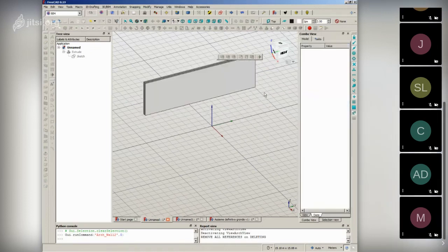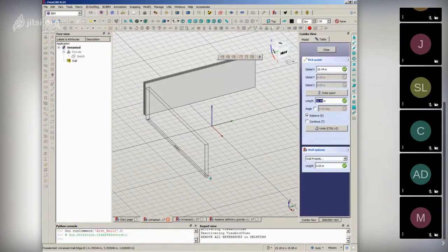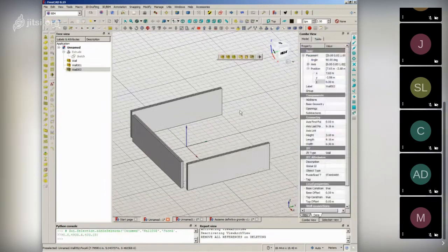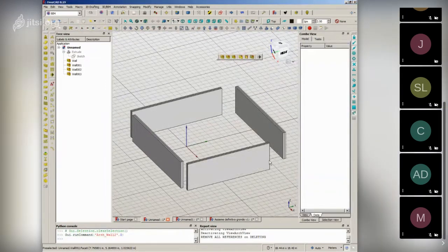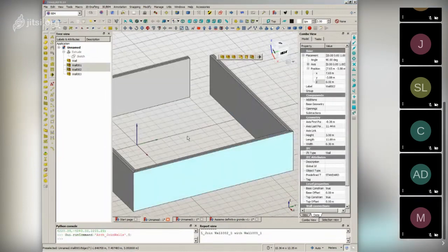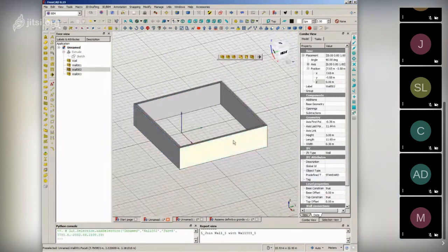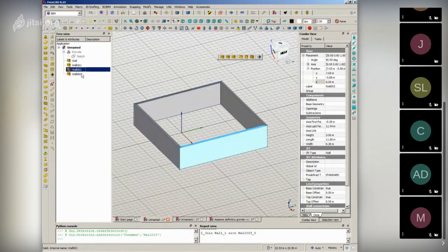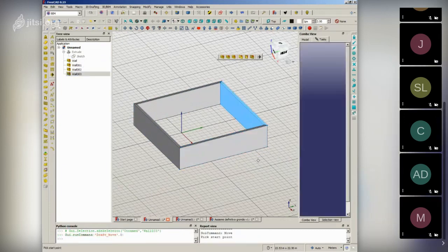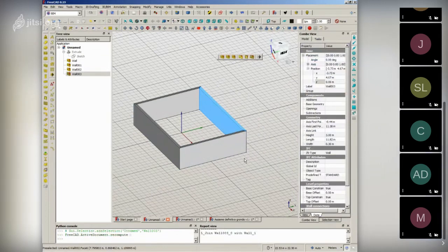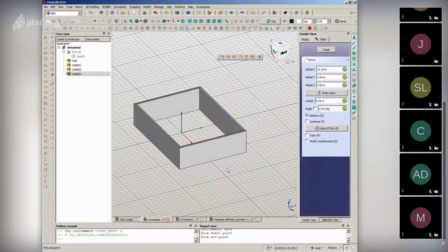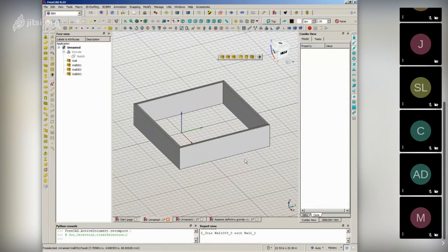You can just draw a wall, like you did before in the Beam Workbench. And then you have the possibility to join two walls with a corner joint, for example. These keep knowing that one wall is joined to the other, and they are separate objects, not as it was used to be done in Beam. So when you move a wall, FreeCAD automatically recomputes the position of the connected walls.